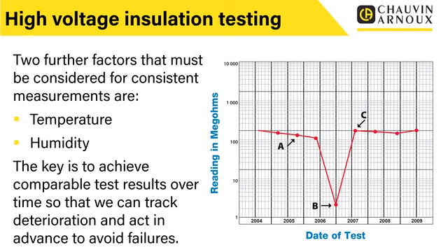Another thing that also makes a difference is humidity. We could be talking about the humidity of the air or even the humidity within the insulation. If there's moisture within the insulation, this can create a problem. It may not be that there's actually a problem with the insulation. It may just be that it's been in a damp environment, or it's been cleaned, it's been washed. It could have been exposed to water. There could be all sorts of things where it may need to dry out over a period of time.